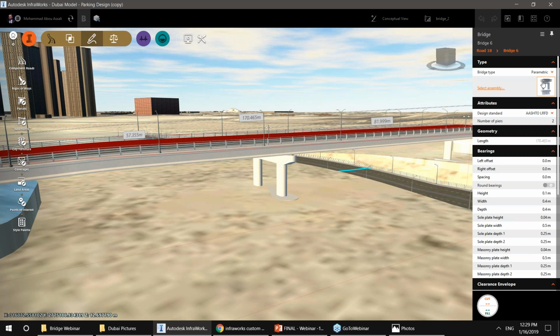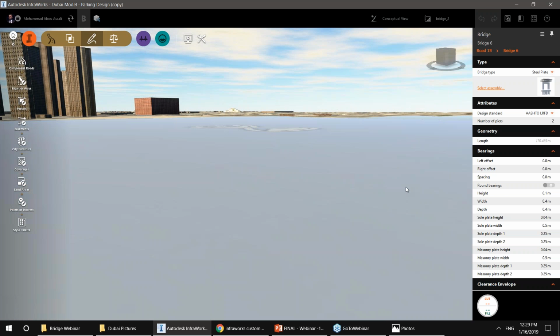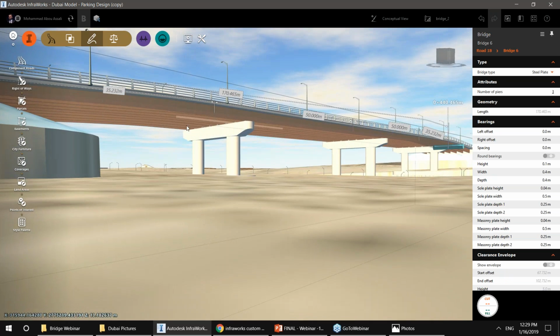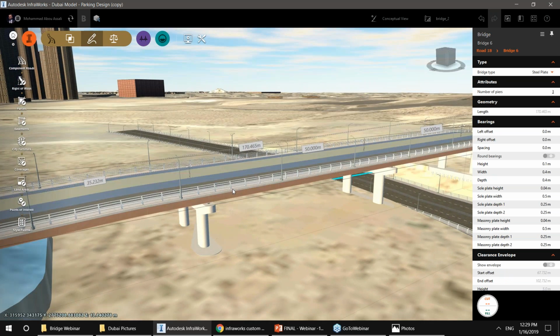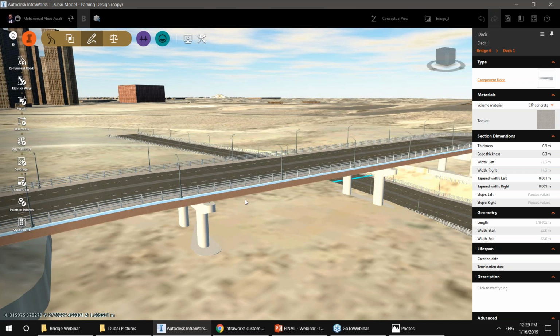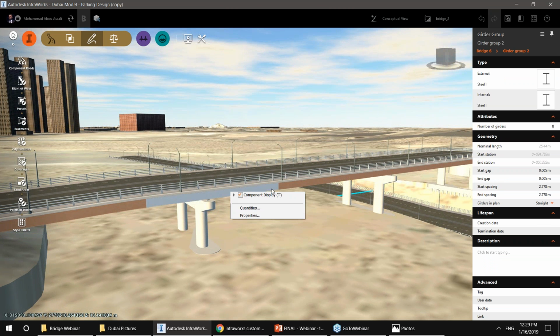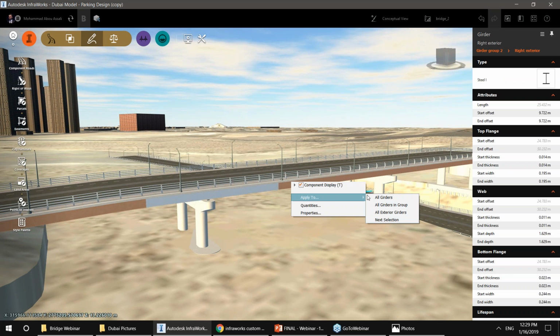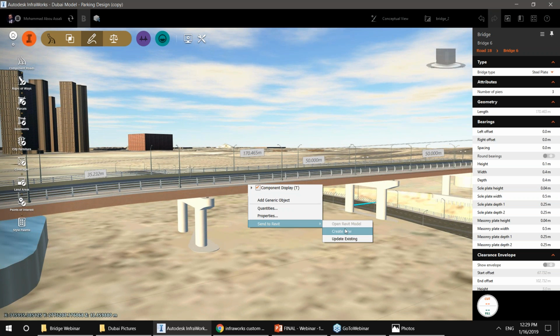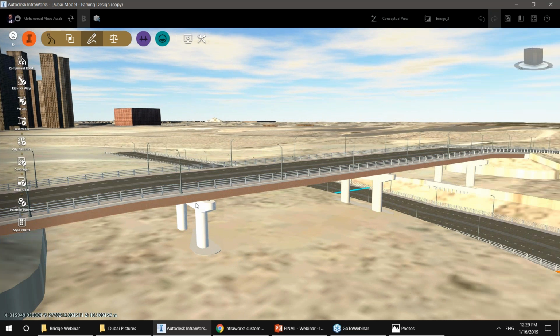What if I change the type of the bridge and I take a steel plate bridge? So I have another proposal. This is proposal 2. Now I have, as you can see, steel girders. If I click on the bridge, right click, quantities, I'll have both the concrete and the structural steel required for the steel girders, but not for the reinforcement. Okay, all calculated for me automatically. If I also right click at the bridge, I can apply so many things, or else I can send the bridge to Revit automatically for detailed design, which we're going to see later. Okay.